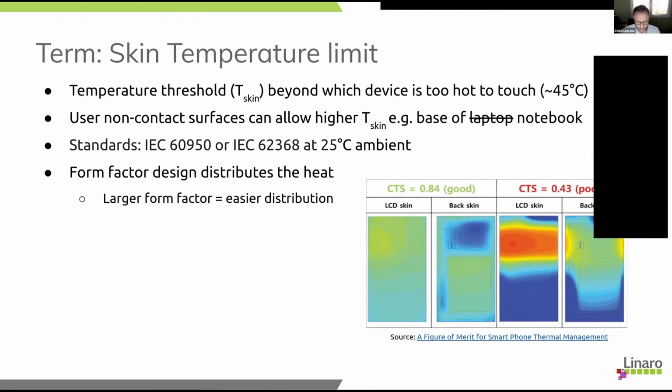This temperature must not go beyond 45 degrees, more or less, because if you have something on your skin at a temperature beyond 50 degrees for more than 30 minutes, it results in a first degree burn.